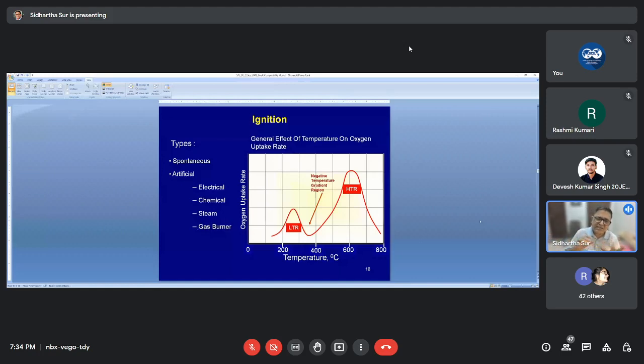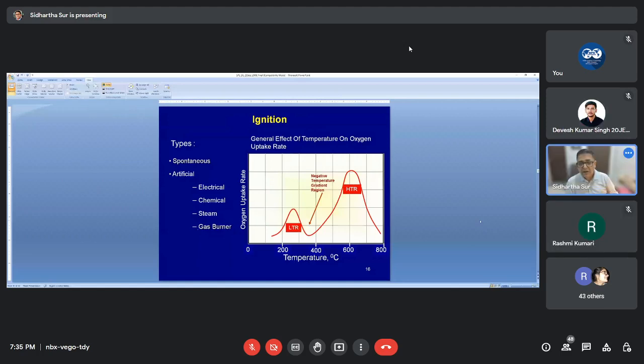When you see HC plus oxygen, complete combustion gives CO2 and H2O. So in this portion, all the chains are broken. This is called bond scission reaction. And the entire operation in this region is desirable in the field. So you have to maintain a sufficient quantity of air in the injection during field operation, and you have to maintain bond scission reactions in the field. How to know that? You will know because carbon dioxide will come out.